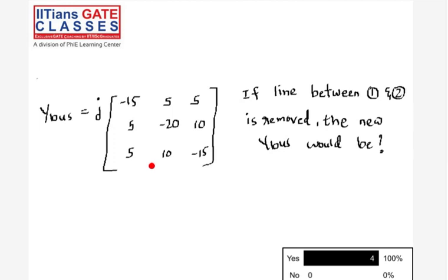From a programming point of view, a sparse matrix is easy to compute with and easy to store. You need only a very small amount of storage. So when we are doing load flow or other system studies, it is easy to do that with a sparse matrix like this. That is why we are studying how to form the Ybus, and we are representing the network by Ybus. Is that clear?